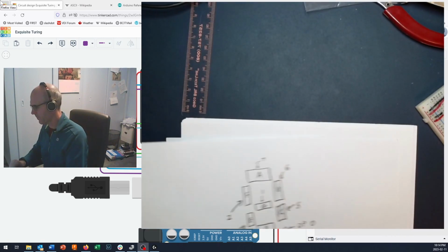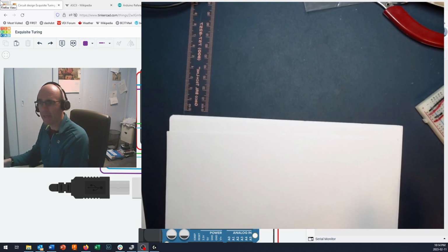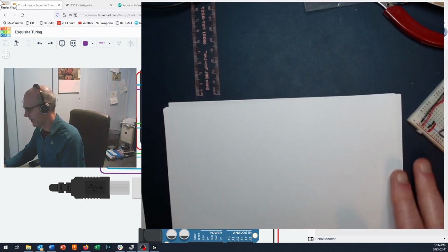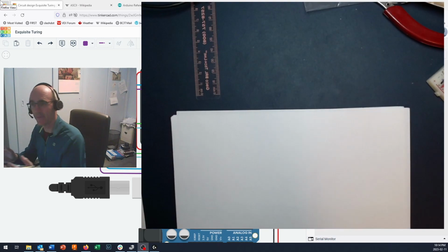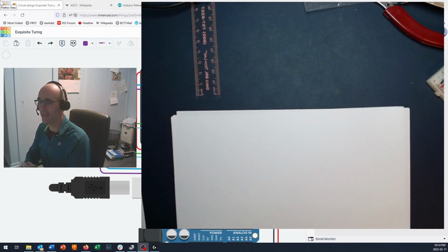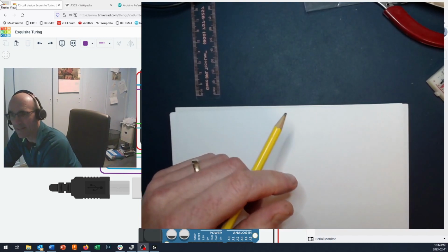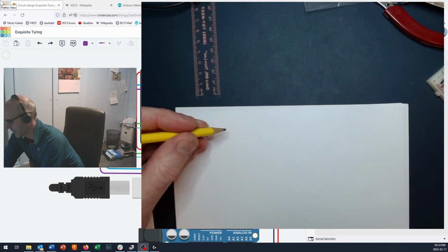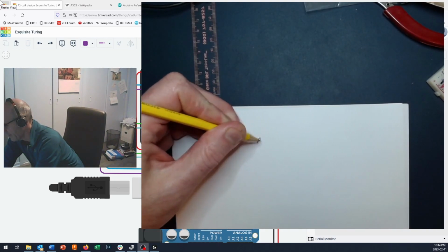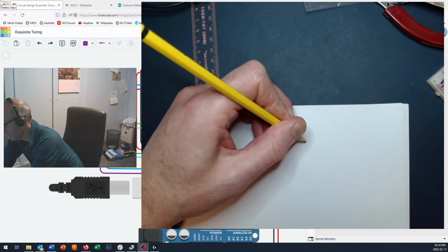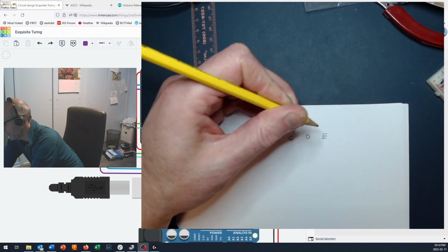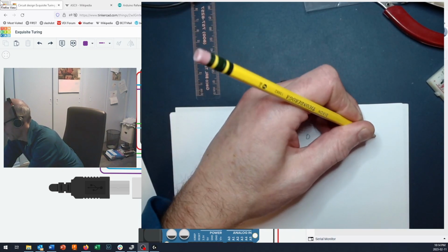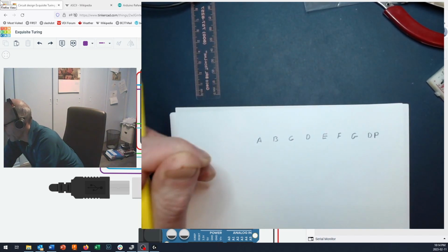So you'll recall that a 1 byte binary number has 8 bits to it. And this is going to come in handy because not coincidentally, very intentionally, we've got 8 bits controlling what's going on our display. So what have we got going on our display? Well, we've got A, B, C, D, E, F, and G segments plus the decimal point right there.